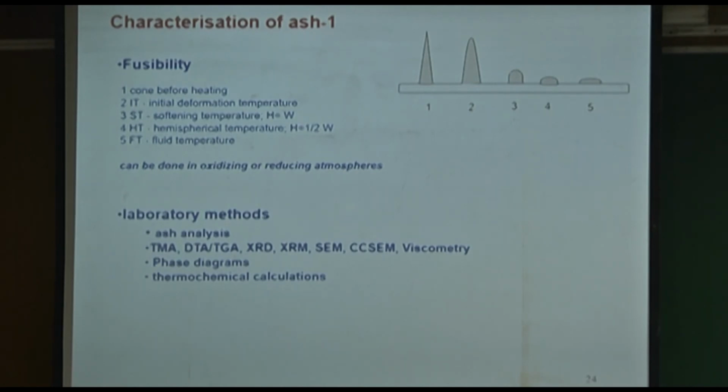So you can actually predict: you give an ash composition, tell the software in the input file what the atmosphere is like, whether it's nitrogen or CO2 or any other reducing gas or steam, and do the calculations at different temperatures. It will tell you what compounds are going to form under reducing atmosphere versus oxidizing atmosphere as a function of temperature. That will give you the first indication. And then, of course, the proof of the pudding is in eating.